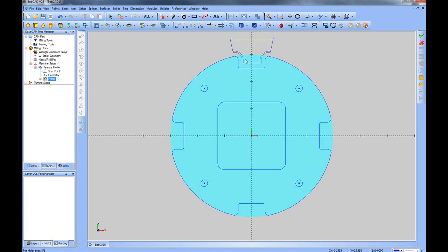Let's go ahead and just add some geometry to this selection instead of creating individual toolpaths for each cut. We'll right click on Geometry, left click Reselect, and we can see what's been selected turns red. Let's go ahead and add these shapes. So we'll click the first line and then shift click the last one and do the same for each side.